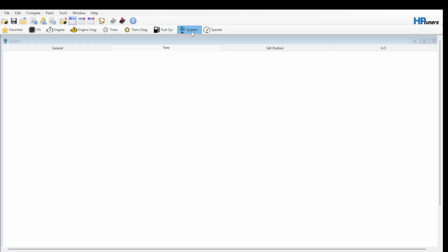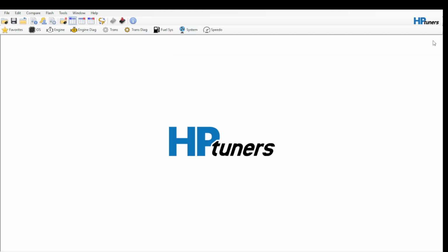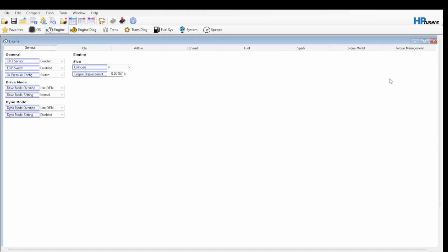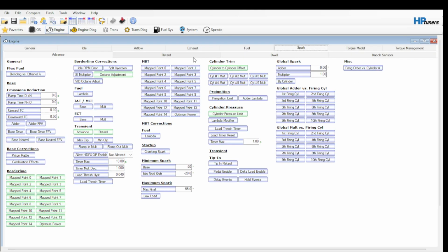Other than that, it's got a 160 degree thermostat, so you'll see that my desired coolant temperature is lower and the fan speeds are different and the trans speeds are different because of the transmission cooler. Other than that, I'm trying to think of any last things before I sign you off.